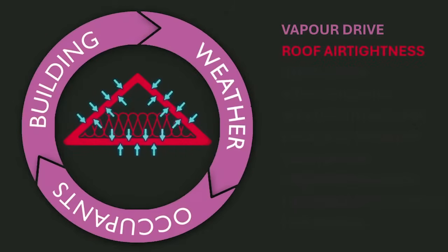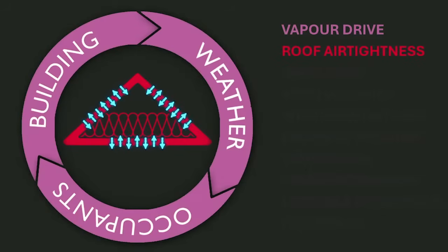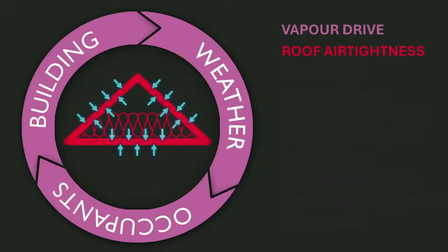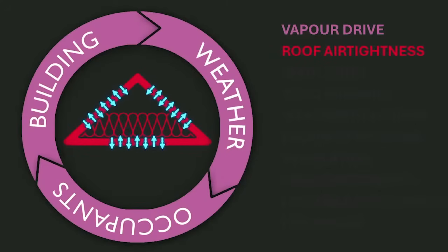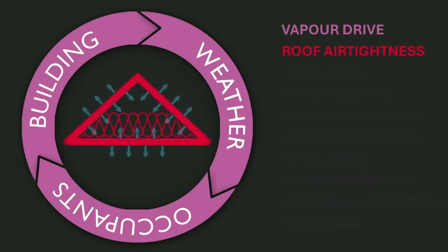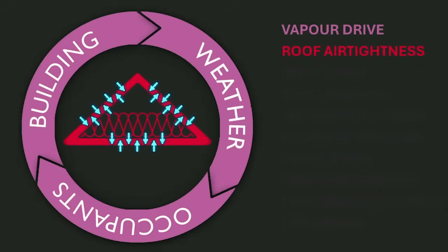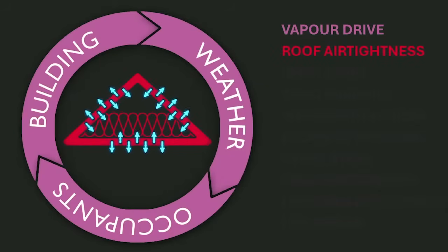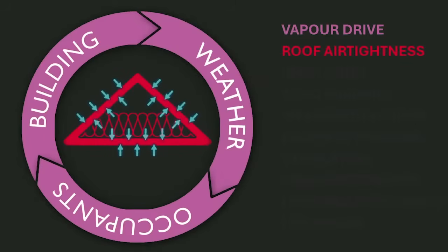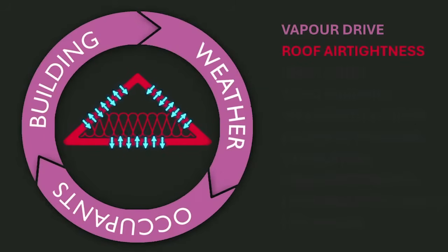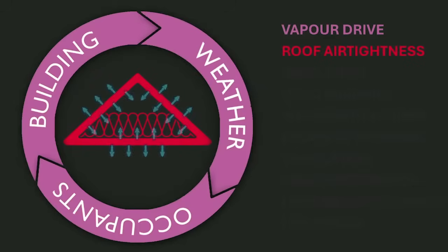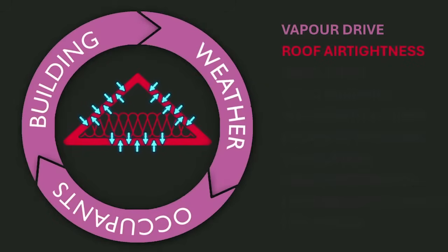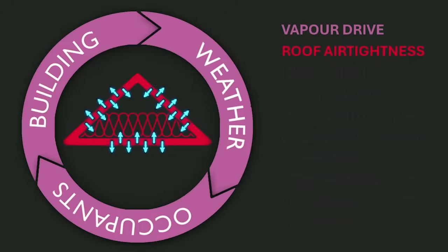Airtightness of the roof. The airtightness of the overall roof construction, as well as the individual components, is also an important influencing factor. Whilst the vapour drive present in a project establishes the question of what condensation risk is present, the air leakage rates involved begin to shape the best answer. If the energy performance assessed in the Home Energy Model, or SBEM calculations, requires a low air leakage rate, that may influence the choice of roof construction or the components specified, as some types of roofs can achieve lower air leakage rates more easily, particularly if extremely low air leakage rates such as those found in Passivhaus homes are required.